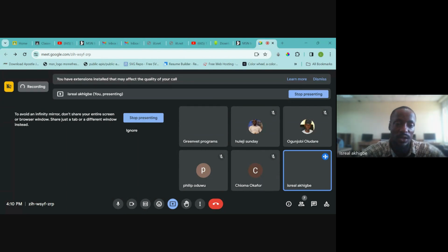So in the case of belts here, just like your gear, which is a type of transmission component, belt is also a transmission component that works with a pulley to help us get rotary motion from our driver. Remember, anything that gives us that source of rotation is your prime mover or your driver. So from our driver, our pulley and belt come into play to help us link our driver to the driven. I just said that the power transmission relies on the coefficient of friction between belt and pulley.